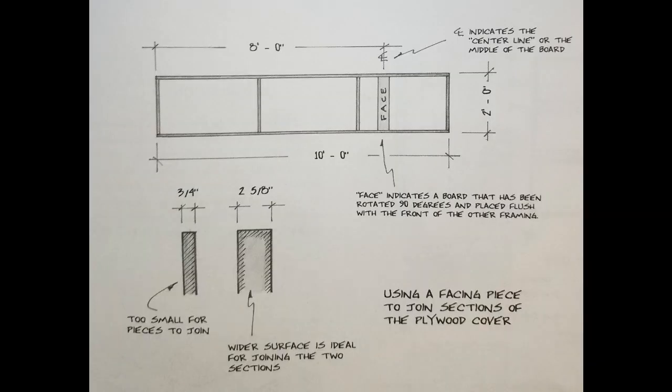There are often times in which you build a wall or a unit that may exceed the 8 foot mark or measurement of most sheet goods. While we typically don't do this for stage platforms, walls, however, are a little easier to work with. So what you would do is at the 8 foot mark, you would add what is known as a little catch plate, and that is where a small piece of 1x or other material is laid on its edge to provide more surface area for two pieces of Luan to actually be attached to.